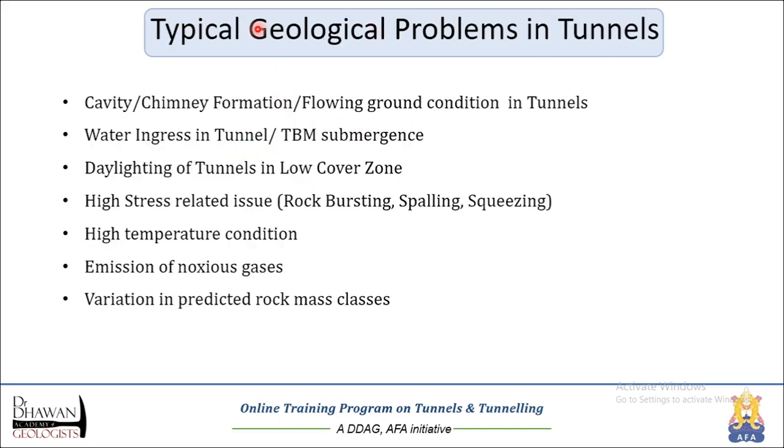And typical geological problems which we have faced during construction of tunnels. The first group of problems can be grouped as cavity formation, chimney formation, flowing ground conditions in tunnels, high ingress of water in tunnel or TBM submergence, daylighting of tunnels in low cover zones if quality of investigation is not good or inadequate.